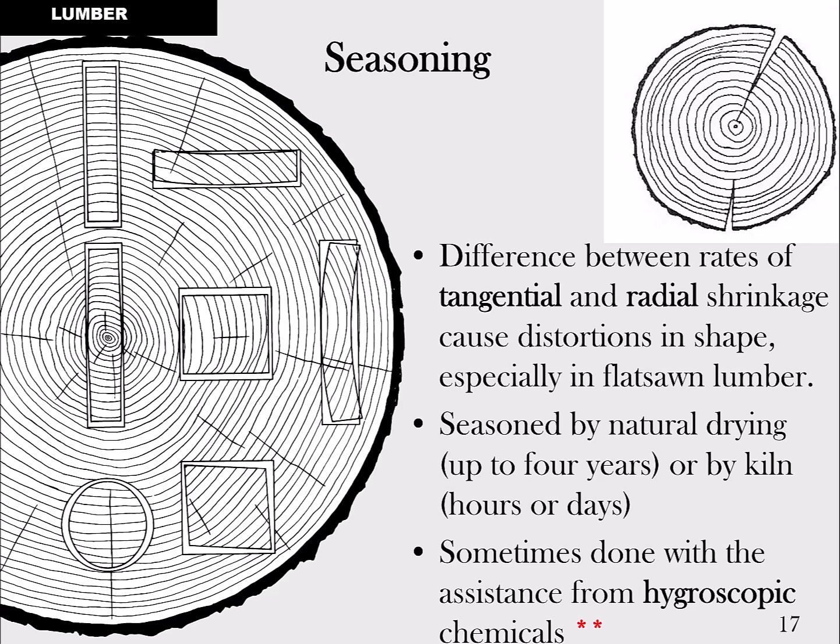Now there's another one right below it that's also considered quarter-sawn, but it's running through the heart of the tree. And when that happens, it's denser material, so it'll tend to be a little chubbier after you cut it and then it shrinks. That's what the lumber yards do. They cut the lumber, they rough cut it, and then they kiln dry it. And this is the kind of shape you can expect out of it.